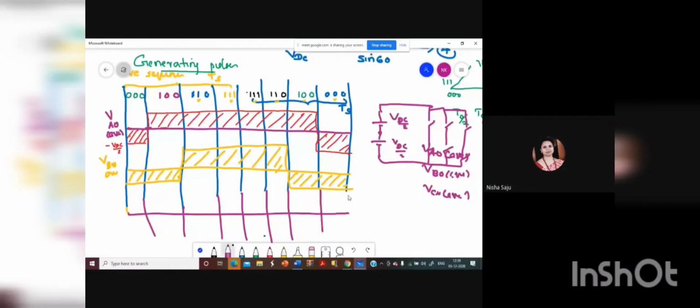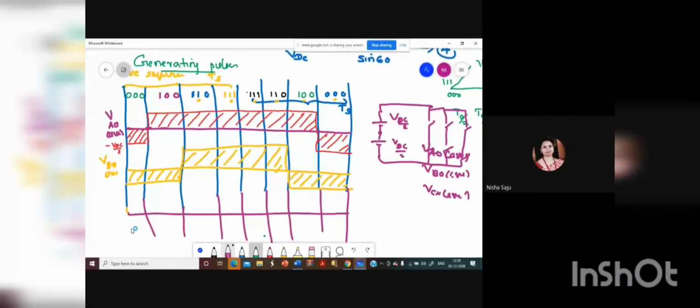Here you will have 0, 0, 0, and here you will get 1 and 1. So up to this level it is 0. Then you will have the maximum 1. Then these 2 points you will get the maximum. Then it will be negative because at all these points you are hitting 0, 0, 0 in the C phase. So this is your VC0 average corresponding to sector 1.